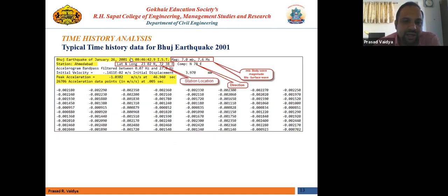and then the date, then time instance, and then you will get the magnitude. There are actually two magnitudes. One is the surface magnitude and another is body wave magnitude. So you can see here 7.0 MB is written here. MB means body wave magnitude, and 7.6 is MS. MS means surface wave magnitude, right? So two magnitudes will be mentioned.